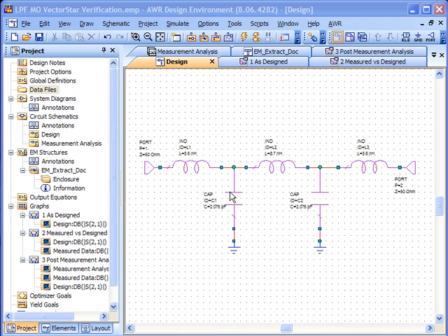In this example, what we're going to do is design a low-pass filter, an LPF, and that LPF has been fabricated. We're going to design it on the VectorStar. We're going to measure it with VectorStar and then bring those measurements back into Microwave Office right on the VectorStar platform and compare our measured versus our design, and then analyze the design a little bit to try to bring the performance back in line with what we're actually measuring, try to understand what's going on on a printed circuit board. VectorStar is a great platform for doing this because you can run Microwave Office simultaneously with doing the measurements.